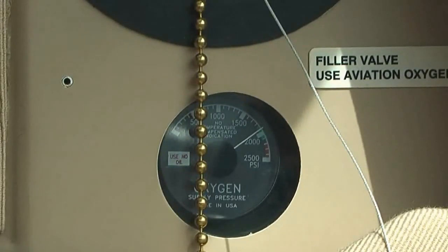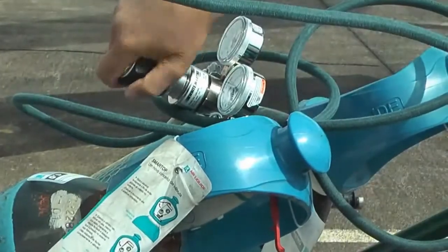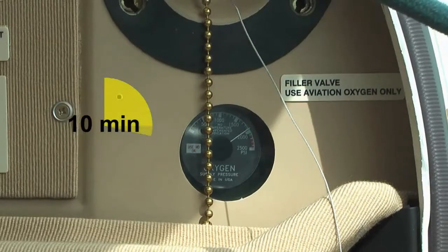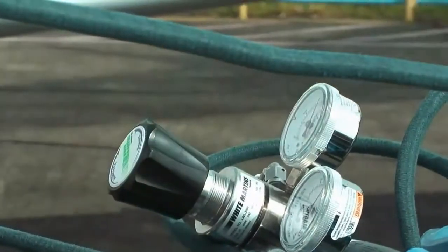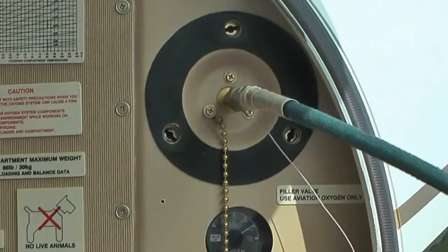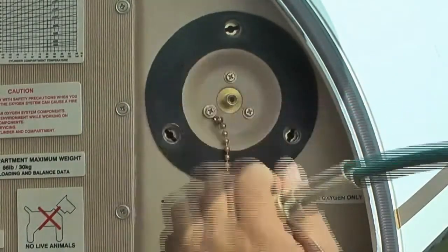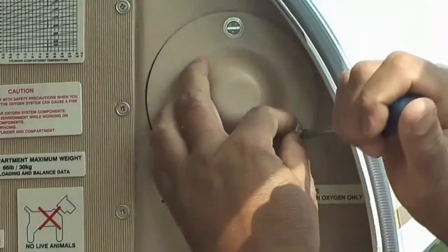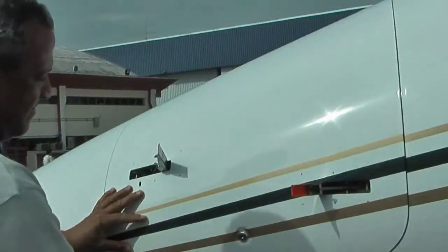Monitor the pressure gauge of the aircraft and of the high-pressure oxygen servicing regulator. Wait at least 10 minutes to let the temperature of the oxygen cylinder become stable. Close the oxygen servicing regulator shutoff valve. Carefully disconnect and remove the oxygen charge adapter from the fill valve to release the remaining pressure in the hose. Reinstall the fill valve protection cap. Close the oxygen compartment door.